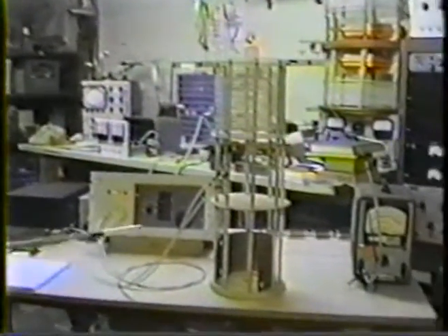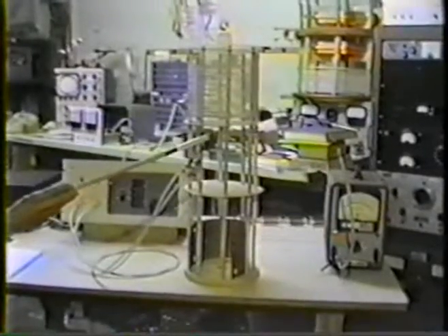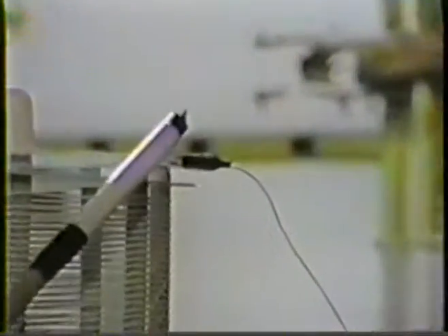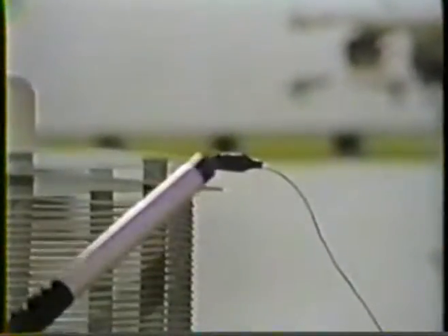And we have, of course, the same generator as before. And then focusing in on the coil here, we see we have a primary turn, which loosely couples to the secondary, or the actual coil itself, through the first turn here, and then the rest of the coil pretty much engages in a free oscillation. And then our capacitive pickup is just a clip lead clipped on to the so-called insulating part of the coil.